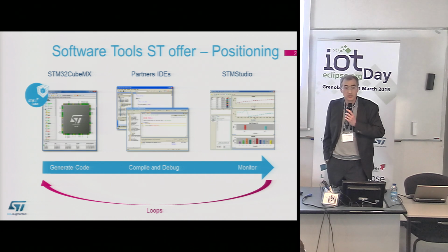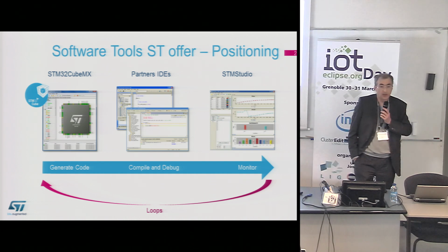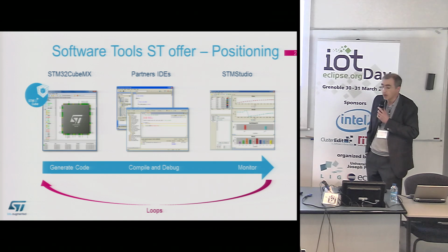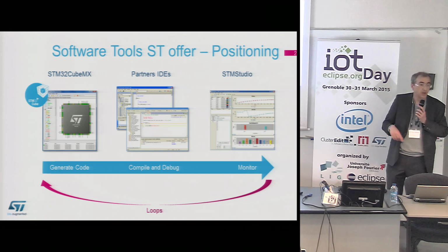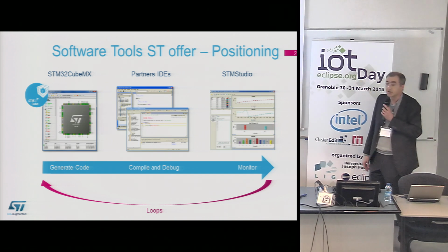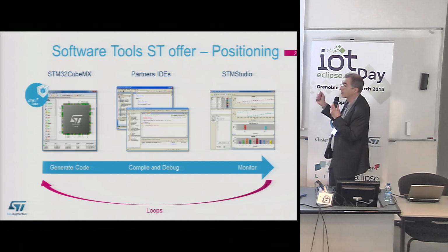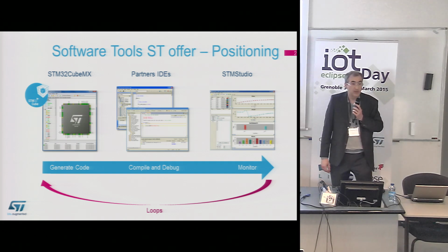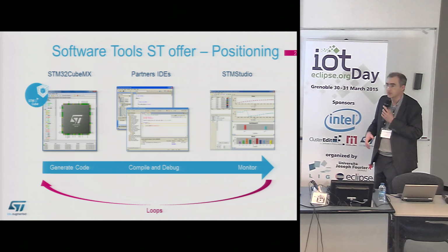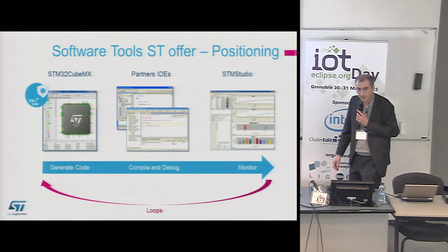The STM Studio tool allows you to dynamically monitor the variables of your application while it is running. Through JTAG, we just read the memory, you monitor, and then you can do graphs and so on. This is used a lot in applications like motor control, because you cannot stop the application with breakpoints, as the motor can go crazy afterwards.